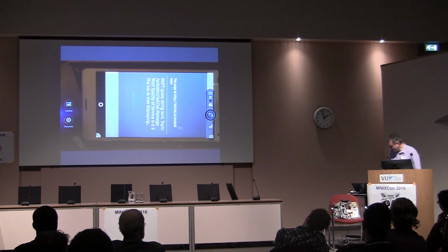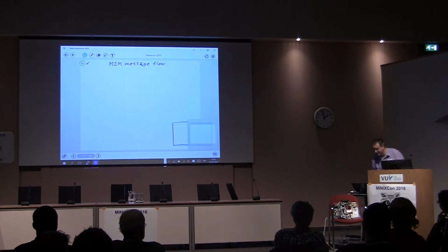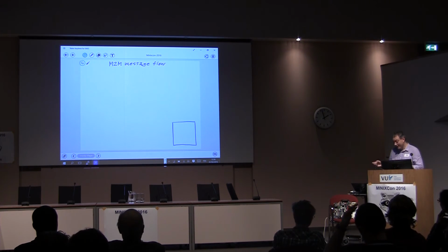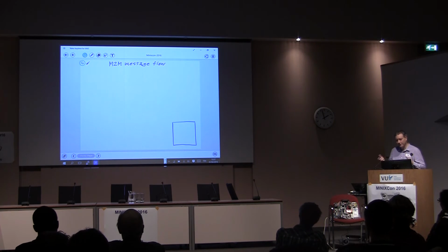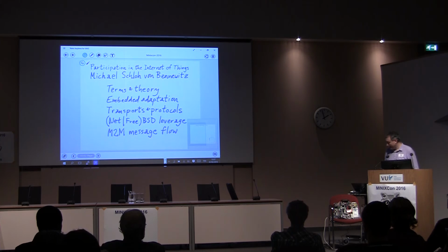And what I usually like to explain once I do that is the message flow, right? But we don't have time for that. So there's a few different transports and protocols happening, like HTTP that's being proxied to MQTT, and the MQTT is allowing machine-to-machine communication to take place over copper and then over Wi-Fi and so on, and serial at the end, because the LOL, or the lot of LEDs, the thing that flashes, is mounted to an Arduino, and the Arduino is connected to the rest of the network over a serial connection, a USB connection. That's how it works.